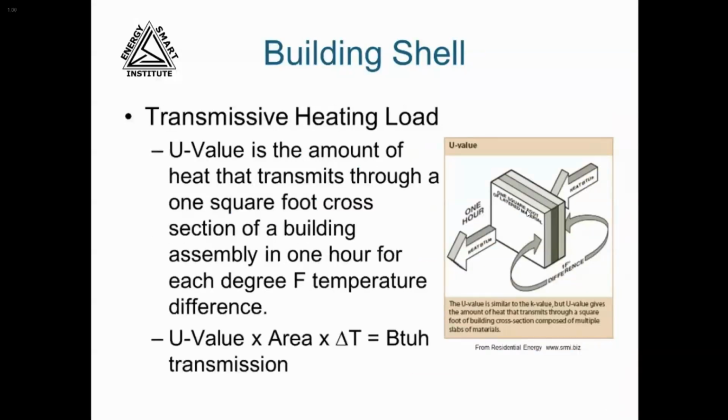Building shell components contain a variety of materials when looked at in cross-section. A wall will have wood studs, some sort of insulation, sheathing, siding, drywall, etc. A stud frame wall is about 20% wood and 80% insulated cavities. The wall's U value takes this all into account as an area-weighted calculation of the conductance of the overall wall.